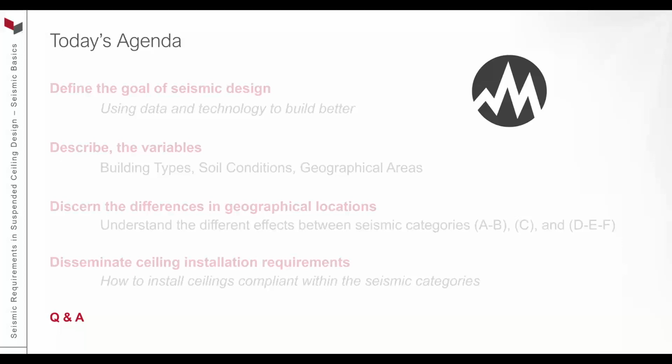At that elevational change, you need to determine which end of the ceiling, say on the lower plane, is attached at the wall, and what is that attachment? Is it fixed or floating? Let's say it's floating. Then at the other end of that ceiling where it transitions up, that needs to become fixed.